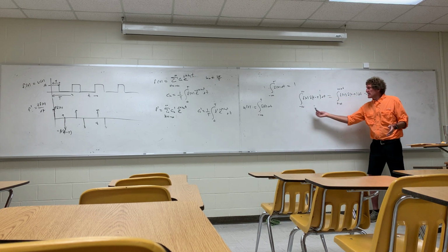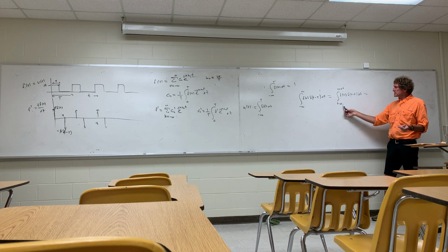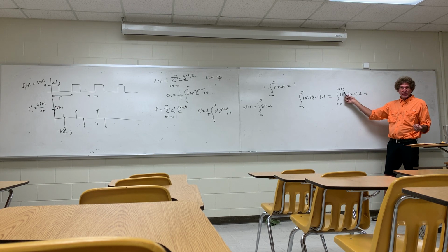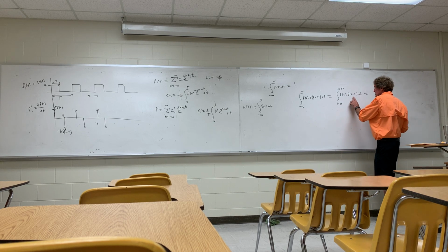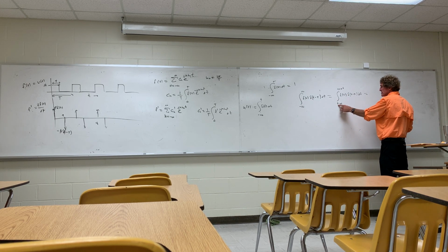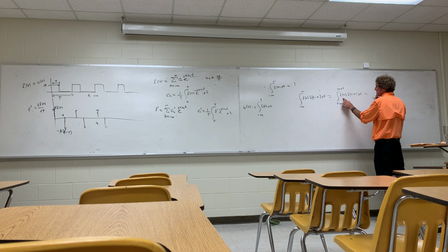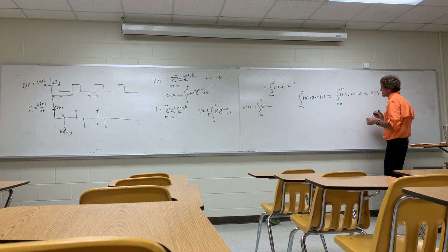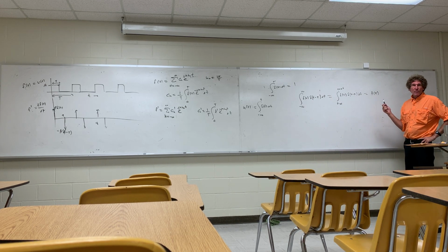Now what I've done is eliminated a good chunk of that integral, and I'm just below where the delta function turns on and just above it. Do y'all follow me on this? Now what's really gonna happen here is this is gonna turn on at tau, which is just an instant. So this really means f is simply gonna be f of tau, right there, times the integral of the delta function, which is 1. My real point is the delta function simply extracts or samples the value of f of t at the point where the delta function turns on. That's all that happens in this integration. Can you appreciate this, guys?